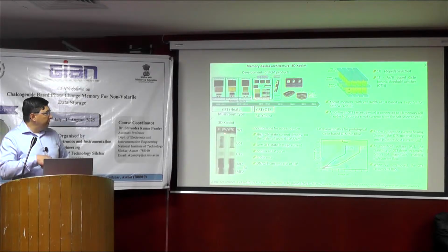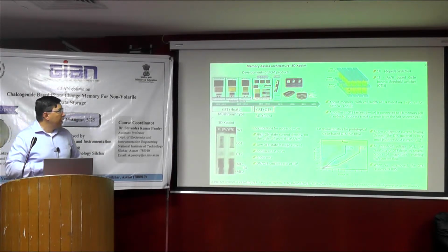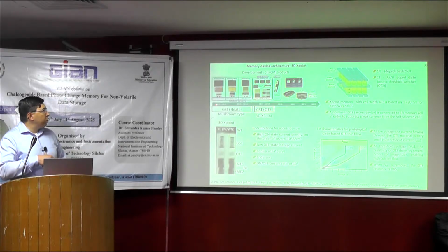So you can see here, this is the GST cell, this is the OTS, the selector, and the bottom electrode word line cell. The development started in 2010 and continued to 2021, and there were also many products based on this 3D technology.